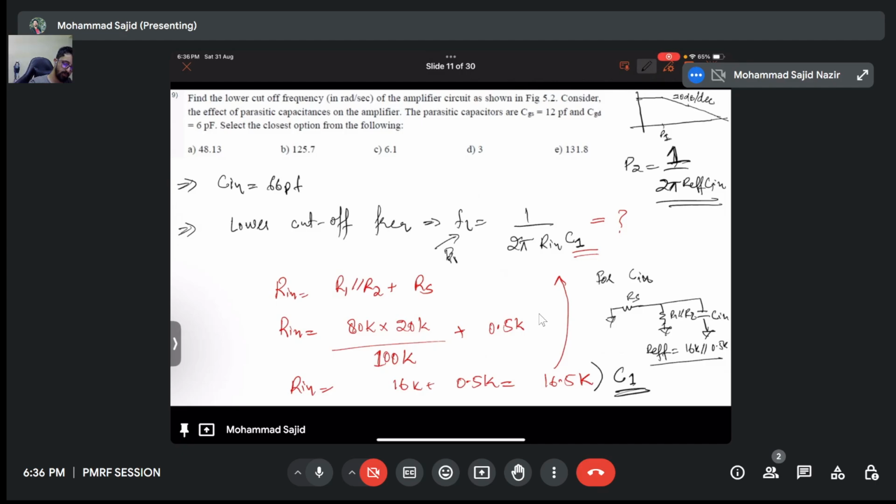Let's say there is only a single pole. If there are multiple poles, it will drop again, say 40 dB per decade with a second pole. If it is a zero, then the slope will increase again. You may have studied this in control systems. So calculate these two poles, P1 and P2, and find which one is lesser, and that will be your cutoff frequency.